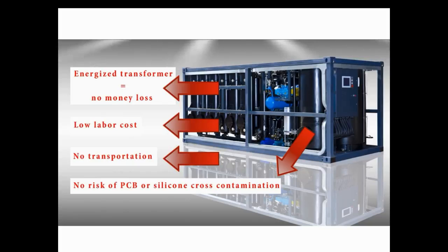It means that contaminants come out of the windings and enter the new oil, so oil degradation starts again very quickly. Simple comparison: if you take a 1 liter bottle of milk and put a little sour milk inside for the night, in the morning the whole bottle will become sour. The same happens to a transformer.